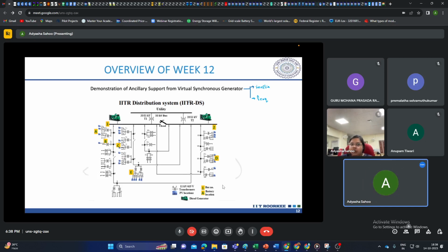We had studied that due to this renewable penetration, traditional synchronous generators are going to retire. These synchronous generators were heavy-massed mechanical systems, those which could store the energy in their rotors and their mechanical parts.